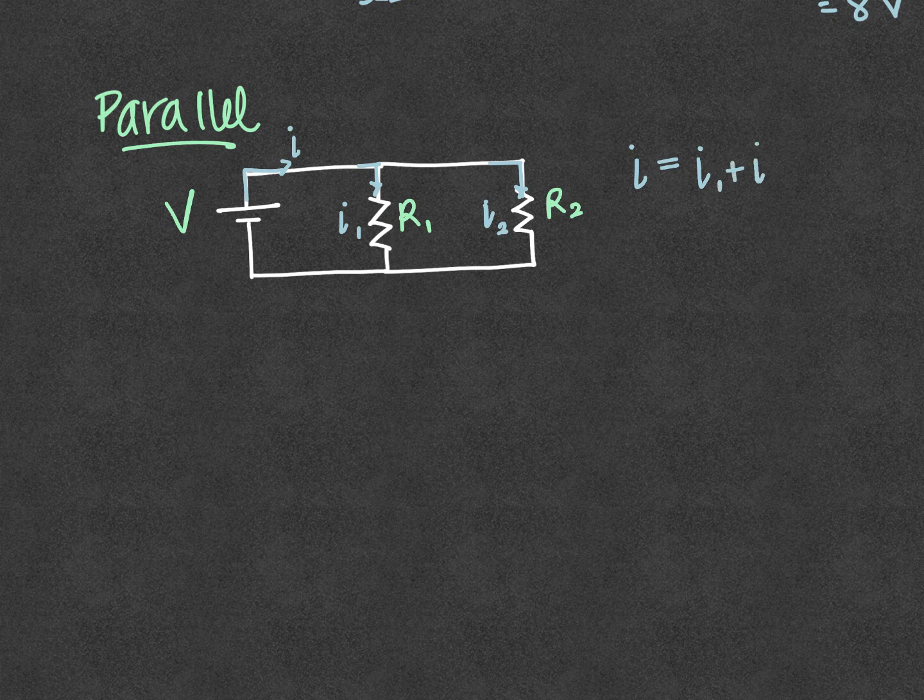and that means that the current through the battery would equal I1 plus I2. So the current adds up, because as the current leaves resistor 1 and the current leaves resistor 2, so I2 comes on around here, and they get together and make I again. This is a rule for any kind of junction. Like this is a junction here where the wires split. So let's look at then the potential difference across these resistors.